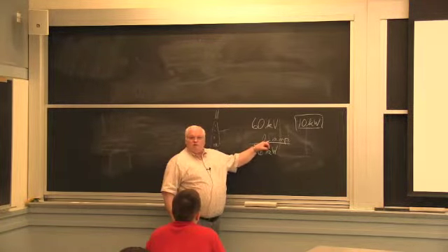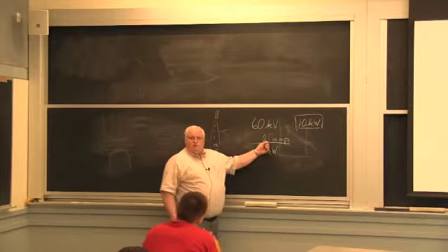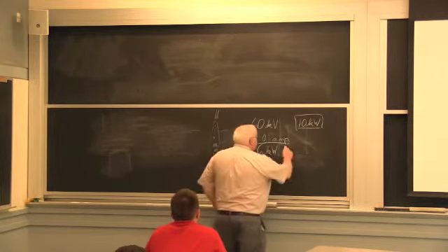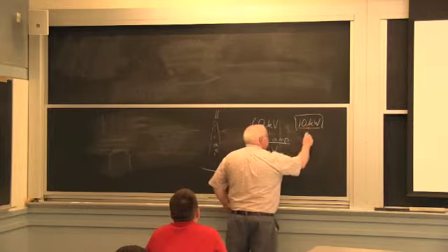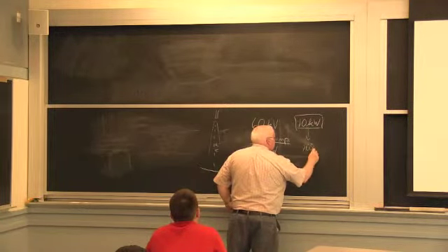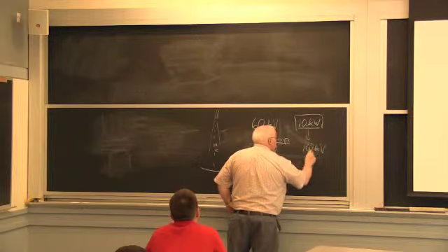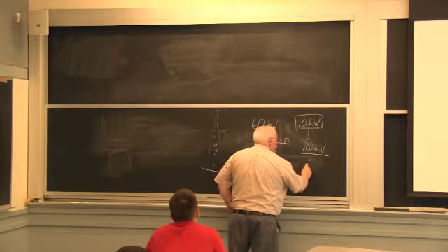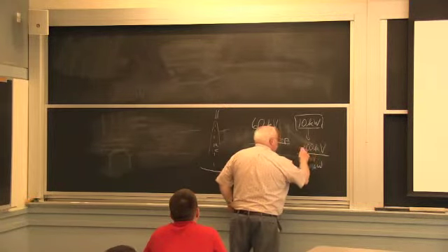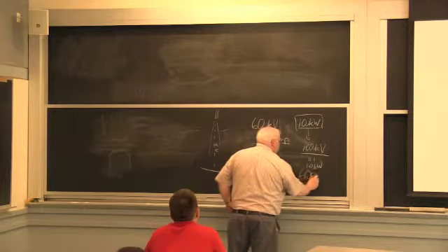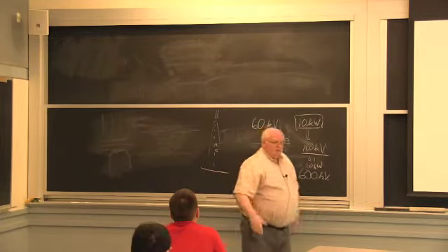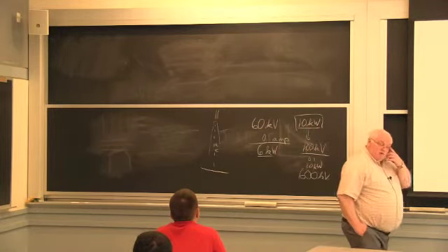above 2/10 or 3/10 of an amp, most machines are limited to about 1/10 of an amp so that you can get good focusing. The electrons are not too close together, which means if I want to go to greater than 10 kilowatts, I typically go to 100 kilovolts in my machine to get that, because now at 1/10 of an amp I can get 10 kilowatts. And in fact, there are some machines, the Japanese built one at 600 kilovolts, and they get 60 kilowatts, and they were doing electron beam in 4, 5, 6, 8-inch thick steel.